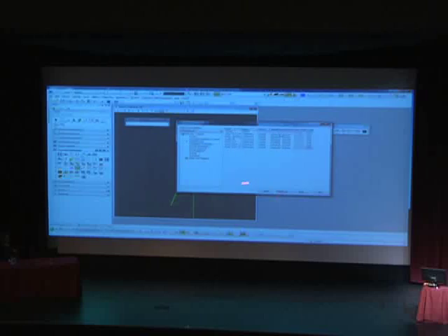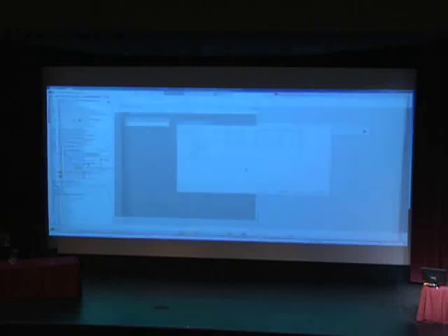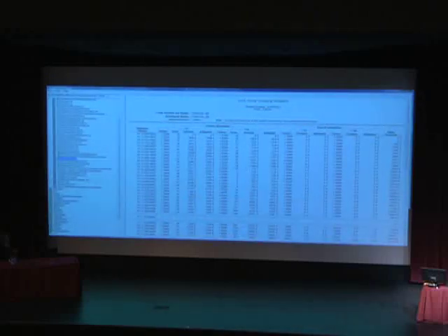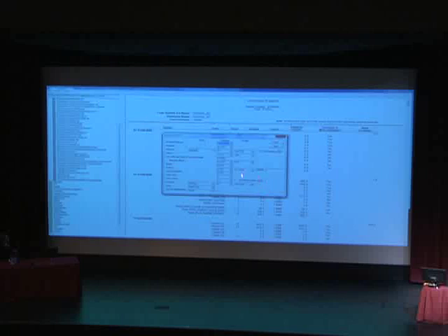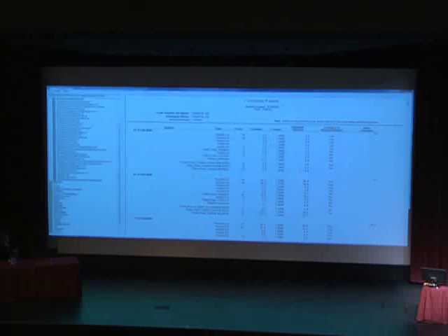So what I'm doing here is I'm just bringing up the earthwork dialog box. I'm going to change all my components, well, one of them, to MDC. MDC basically classifies everything separate from the rest of the quantities. So I have cut and fill separate. And so I'm going to go ahead and go to my volumes report. Now the new report is going to have a list of all my components. It has the volume. I'm switching the units to cubic yards. Just make sure you're in cubic yards. They'll tell you up here. And so there you go. You could actually check your earthwork quantities like that.